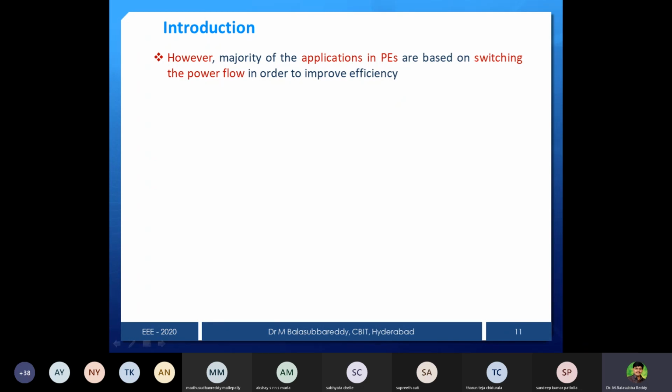Suppose we want to use a potential divider, let's assume that. What is the function of a potential divider? The input is a DC supply. You use a rheostat in between input and output. You want variable voltage in the output. If I use a rheostat, what will happen? Voltage will drop across it and the remaining voltage is connected to the load. You will get a variable DC voltage if I use a potential divider or a rheostat. But what is the drawback? Simply power dissipation. The output is connected to some load. The load draws current. That current passes through the rheostat. Then power dissipation automatically takes place. Whereas here, if I use any control technique, an AC voltage controller or anything, then the switching losses are very minimal. That's why the efficiency of that controller is going to be high.